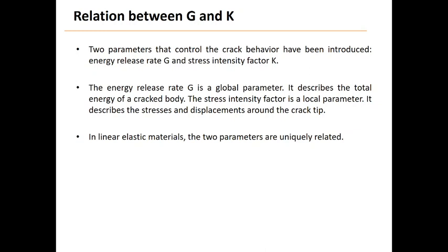Okay, let's continue on, stress intensity factor. The second topic I want to talk to you about is a relation between energy release rate G and the stress intensity factor K. So far, the first major topic that we talked about is energy release rate, and we see how that controls the crack behavior. It is the energy needed to advance the crack by the unit area. And we see another parameter that is stress intensity factor.